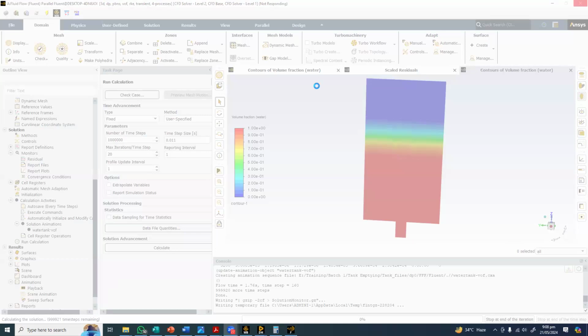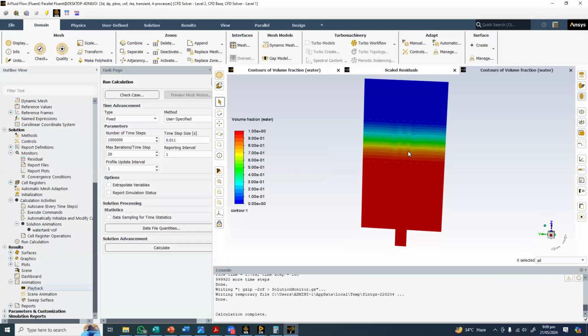But I was saying that we could put a different boundary condition. We can put the symmetry on the top, and the water can go outside, and at the same time air will be trying to enter, because if the air cannot enter, it cannot fill the empty space. Water actually cannot go outside. It's the thing you can observe in the case of any bottle. You can make it upside down and try to exit the water from the exit point of the bottle. You see that some air will go inside. You will see the bubbles there. And then water can go outside.